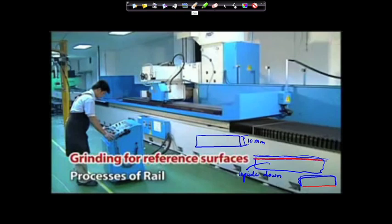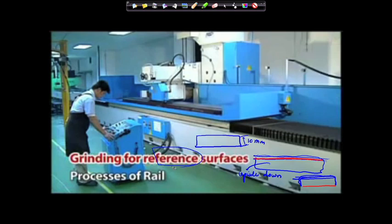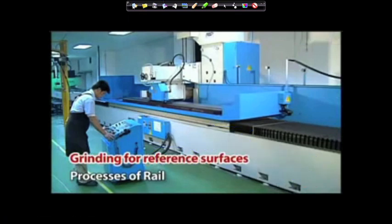Now, you apply that 10 millimeter. So, you measure from here to here how much the 10 millimeter is, and again do one machining operation and one grinding operation, so that you can get the 10 millimeter. So, when your surface does not have any regular shape, you have to create one reference surface, and from that reference surface you continue all the operations with reference to this part. That is why it is called the reference surface. Your calculation of all the dimensions, be it depth, width or length, will be taken care of by this particular surface reference. So, it is required for this operation also.